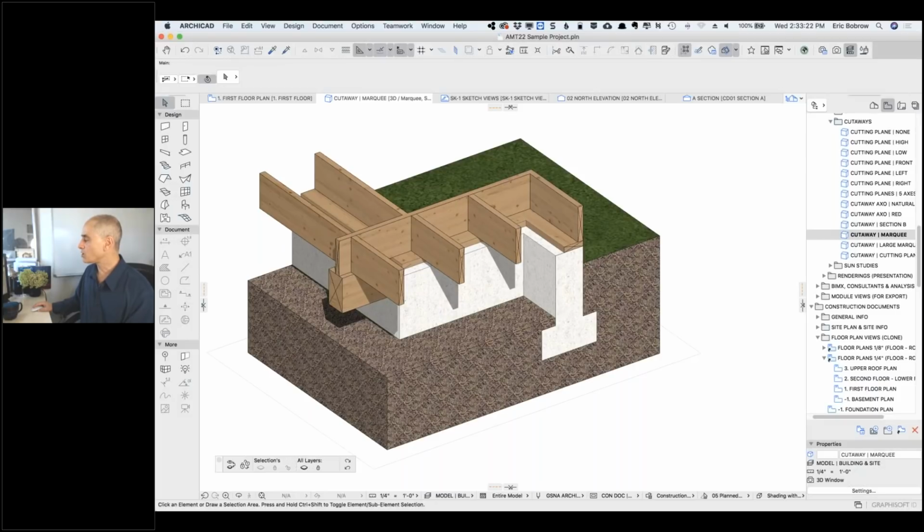Ken Brooks, see-through walls with gray lines. So I'm not sure, that was one of the views a few minutes ago, used a graphic override saying make sure that the walls are glass or airspace, and then the graphic override also said make those walls have gray lines, or maybe it was all 3D elements were gray. So the graphic override changed the pen to a different pen number.